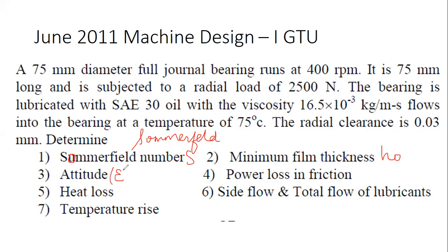Then the power lost in friction, heat loss, side flow Qs in terms of the Raimondi-Boyd method, total flow Q, and temperature rise. Let's start with the numerical.